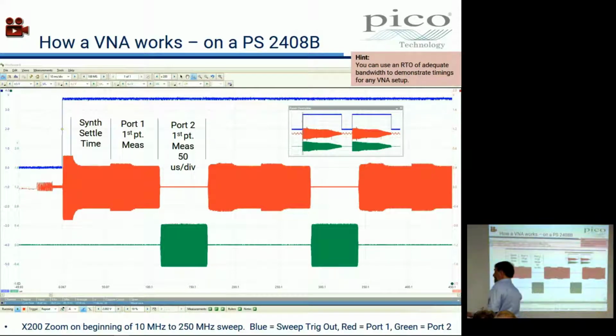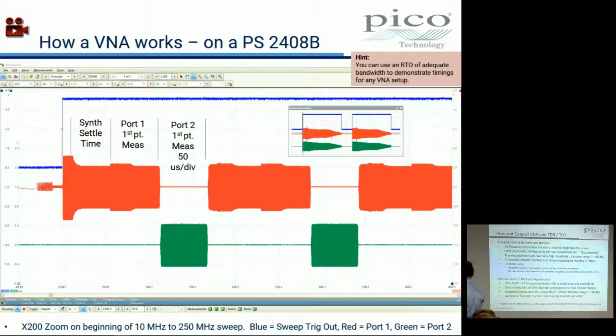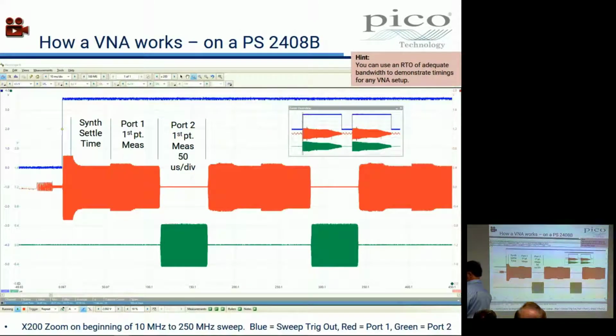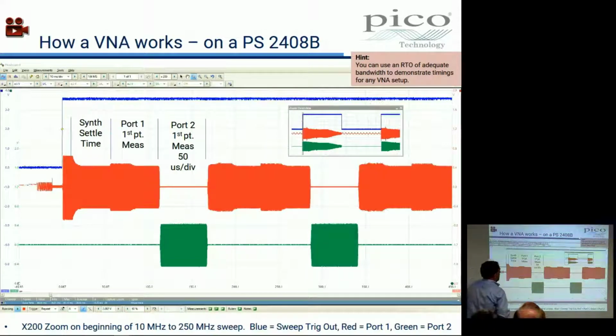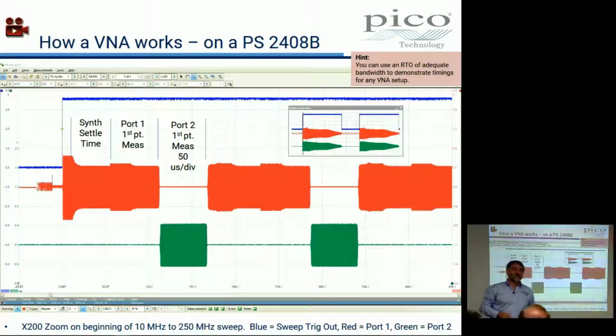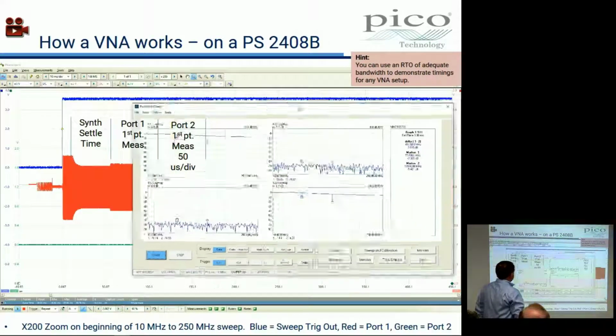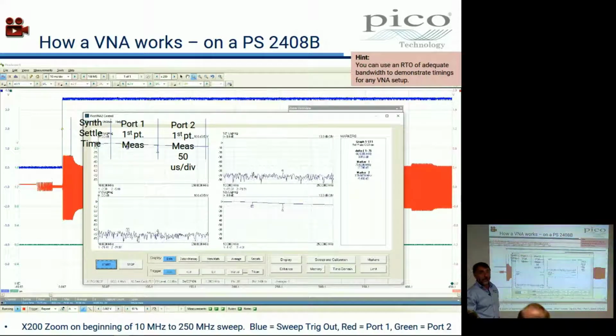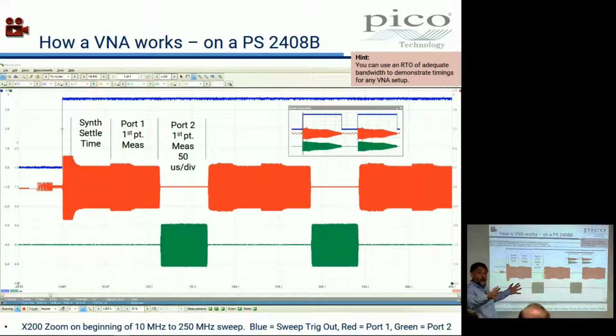And that actually runs as a video, I seem to remember. Whoops. Why doesn't it? It does. I'm sure it does. Yeah, there you go. This is a software time. So you can see that at each sweep start, there's a bit of a software latency, as it were. And here's the update rate that is occurring. You can see that's quite lively, you're getting about 20-25 updates per second on the screen in terms of a whole trace on all four S parameters.